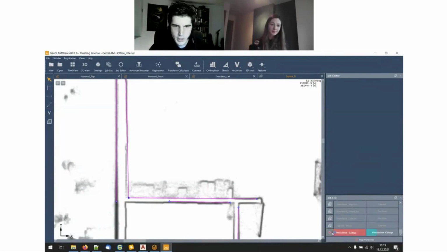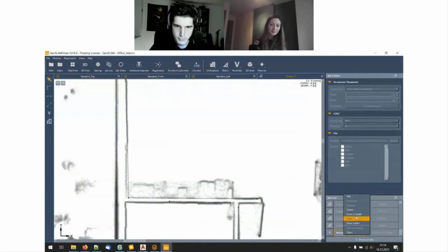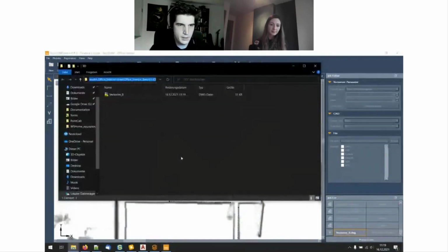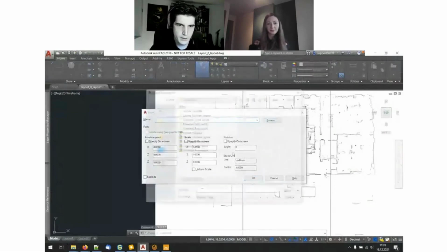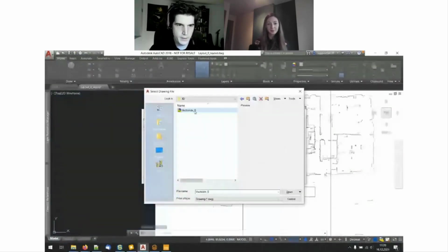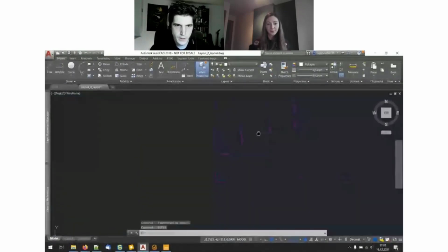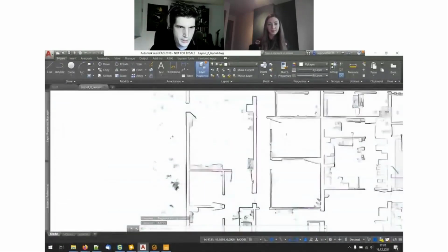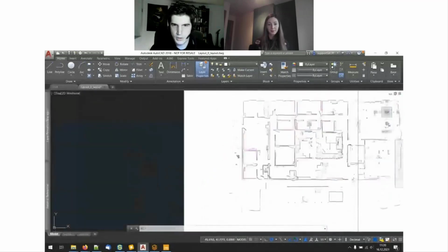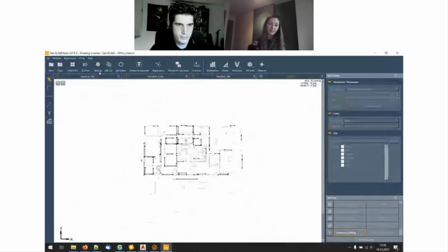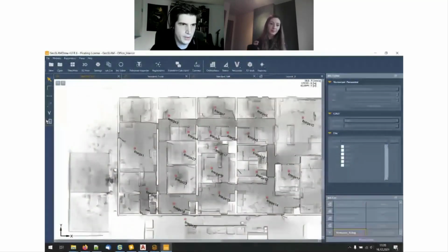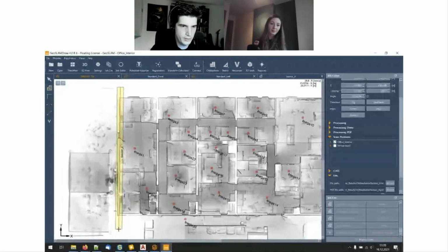And when we are finished, just export these as well. And they are available as a DWG file as well. We could just insert them here. They should be somewhere here. And you see the lines are directly here on my drawing. We have created them in GeoSLAM Draw. So everything is directly available. We can insert sections as well. So if we want to have the height somewhere, let's generate one here.